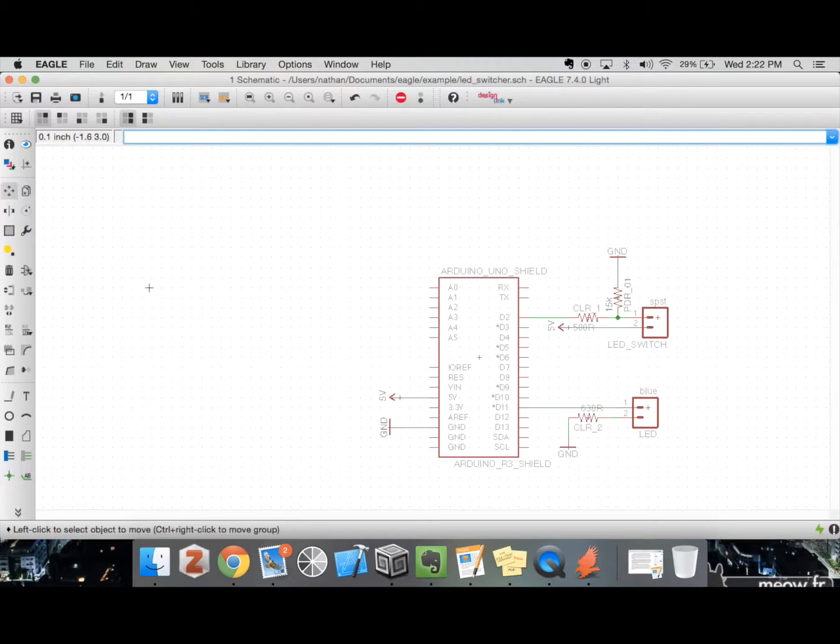But we can actually sever that link and then smash this composite object that consists of these lines and this text here and these pins and the text up here into its individual components, and then we can move those around and arrange it in a way that's more readable or more aesthetically pleasing. So I can type in smash here, and then if I click on the component, you can see that now I have those little crosshairs on the text. And it provides a line showing what component it's linked to. And then I'm able to actually independently move those around. I can make my adjustments. Bam, it looks way better. Fantastic.